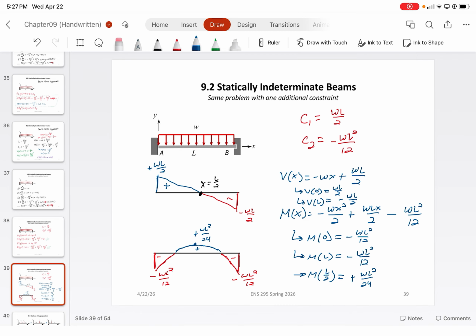Ryan was along the right track of knowing what the inflection points are, because that does affect the way the beam obviously deforms when it switches from a positive concavity to a negative, or a negative to a positive. And we can figure out those values by just plugging in M(x) equal to 0 and solving for x, right? But we're not really too focused on where those exact points are right now. But how would the structure deform? That's what I want to know.